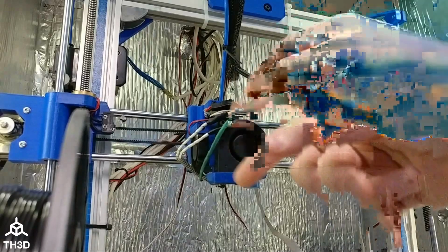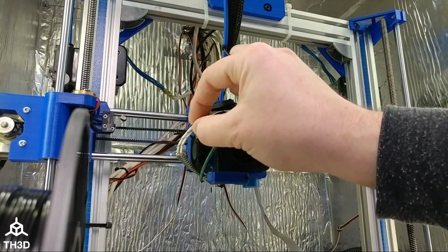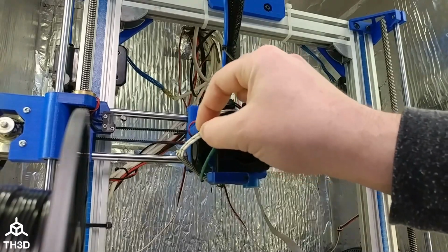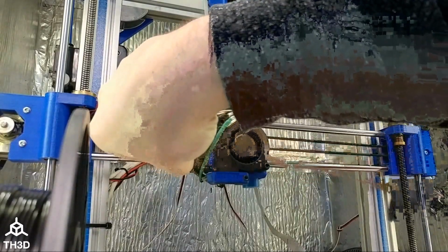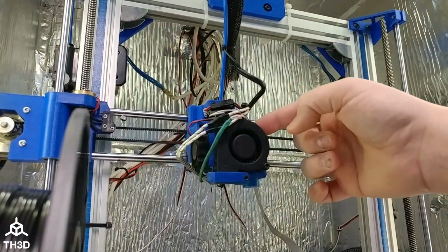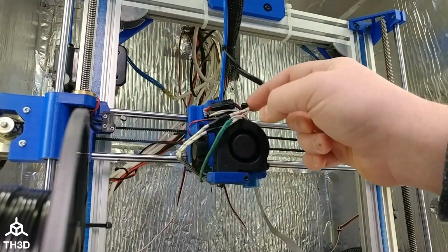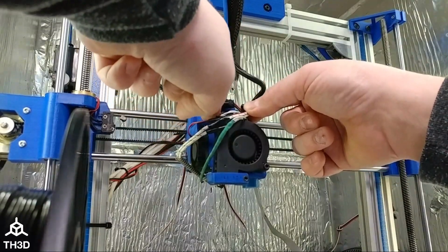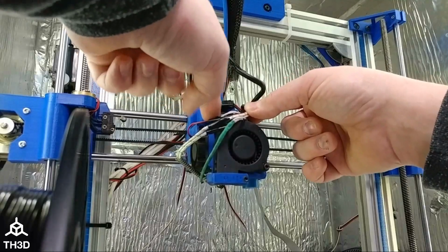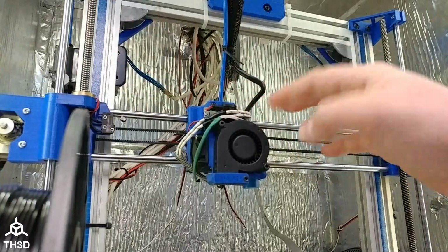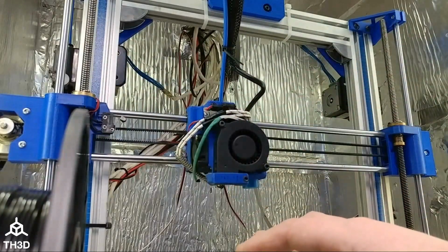No changes. We're still steadily approaching temp. If I move my heater wires here, still approaching temp. These feel solid. They're not like flexed off. You can see here I got them all tied up so they can't move that much anyways. Let's see, here's another. Alright, so I'm not seeing anything here that indicates that there's actually a problem with the heater block on here.